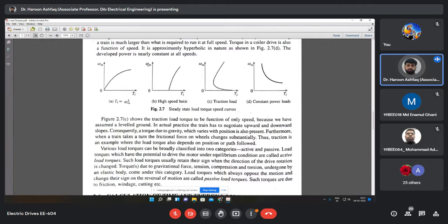ठीक है, अगर चार आदमी को एक जगह से दूसरी जगह जाना है तो चार को ही जाना है. ठीक है, पंखा अगर 300 आरपीएम पे चलना है तो 300 पे ही चलना है. ठीक है ना, तो ऐसा नहीं है कि आप काम चला लीजिए 400 आरपीएम से, आप काम चला लीजिए 200 आरपीएम से. So it is not like that. Whenever you define any load characteristics, it means they are firm and only the motor characteristics are to be matched to the load characteristics. So the motor characteristics are to be altered in all the cases.